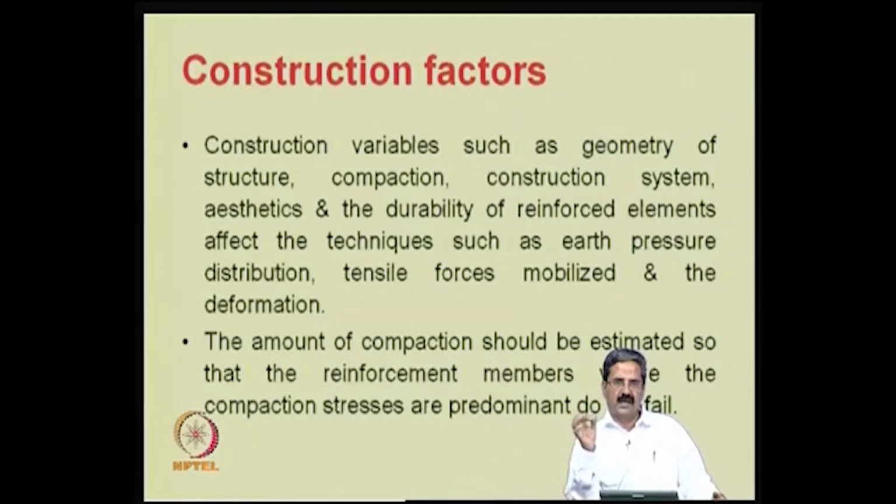So one should understand that a number of factors, such as geometry of the structure, compaction, construction system, aesthetics and durability of reinforcements, all affect the earth pressure distribution and the tensile forces mobilized in the deformation. Finally, they are all affected by the technique itself.